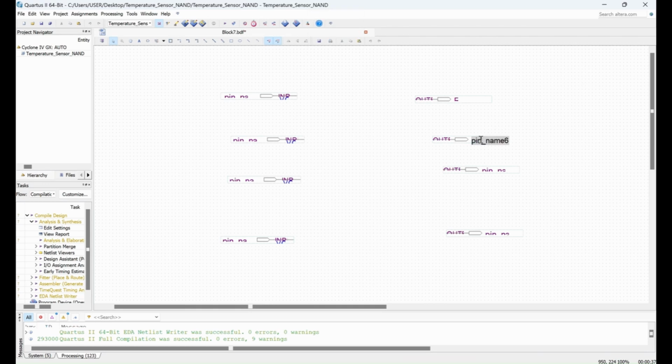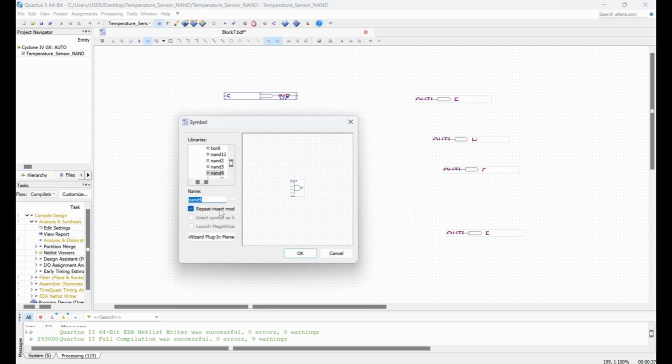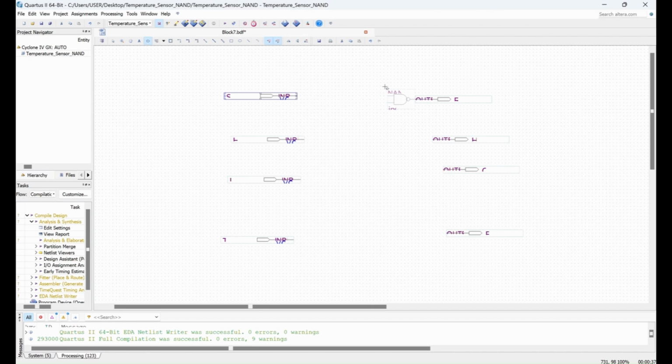This part, we're going to demonstrate how you are going to build the circuit using only universal gates, which in our case, we're going to be using only NAND gates. And first off, we're going to start by putting all of the inputs and all of the outputs and labeling them according to their respective MSB and LSB bits. For the top part, we have the MSB bits, and for the bottom part, we have the LSB bits.